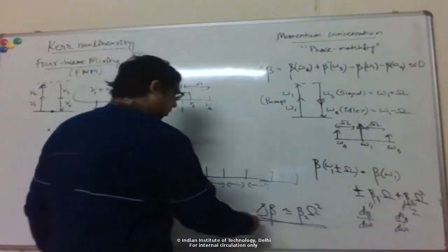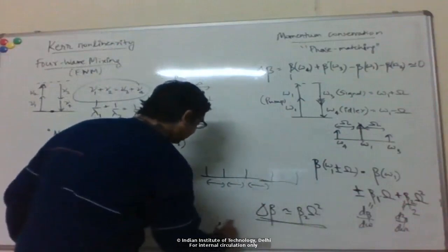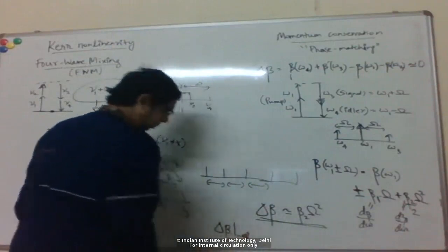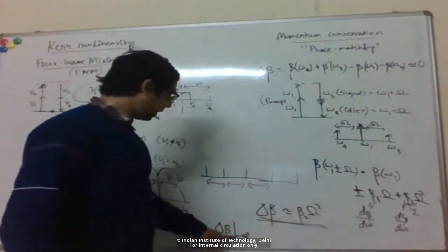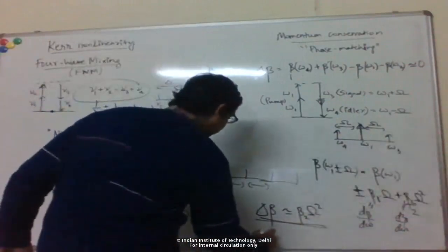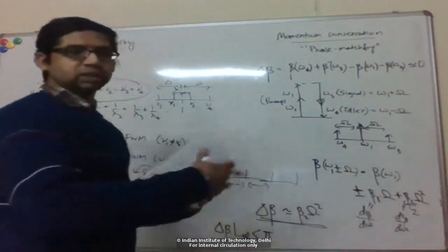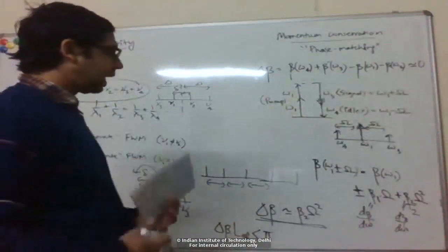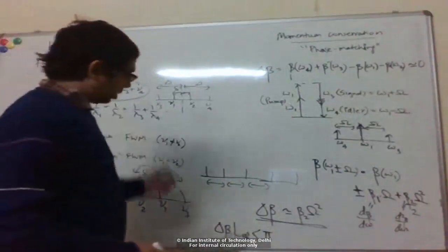Okay, so again, a rule of thumb you can imagine is that if the cumulative phase difference, so delta beta times L effective, this difference in the wave vectors multiplied by the effective nonlinear length, is less than pi, then the process still constructively interferes over the fiber length, and this process is efficient.